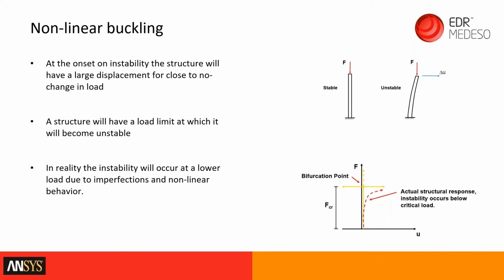The point at which the stiffness becomes 0, there is a theoretical limit, a buckling limit. In fact, a guy called Euler came up with a set of equations that would allow you to calculate the buckling load numerically. And we can do this. The technique is called an eigenvalue buckling analysis, and it will calculate the theoretical limit. The other method is using a non-linear analysis and actually applying the load and modeling the buckling behavior, including the post-buckling behavior. We're going to cover that today.